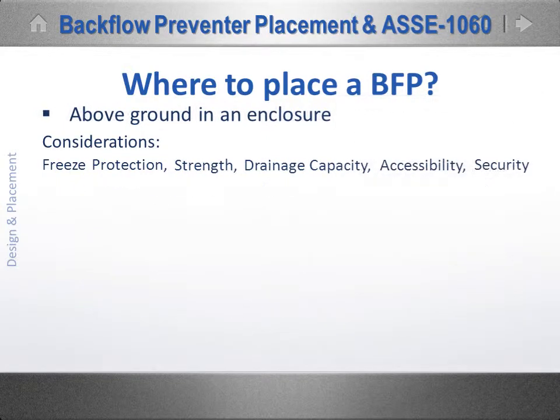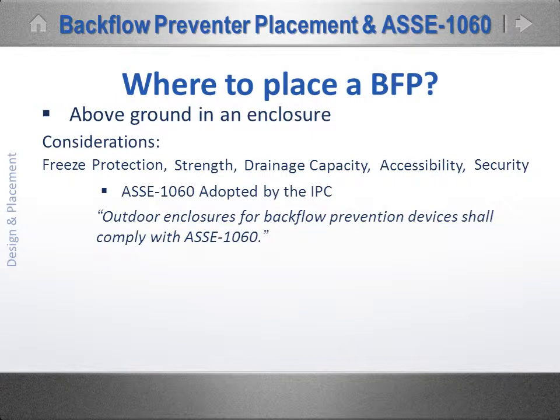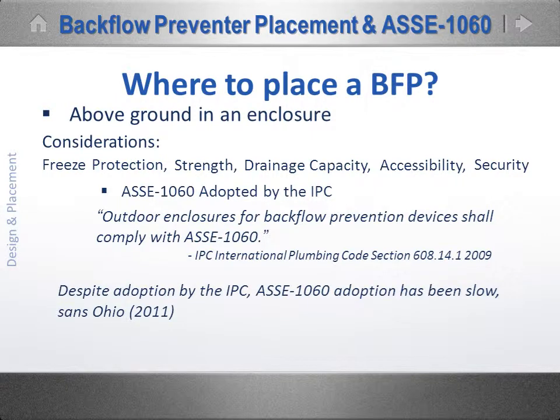Within a few years, the IPC adopted the new standard, and that code simply reads, outdoor enclosures for backflow prevention devices shall comply with ASSE 1060. And despite adoption, ASSE 1060 is poorly understood by purveyors and rarely mentioned in specifications.